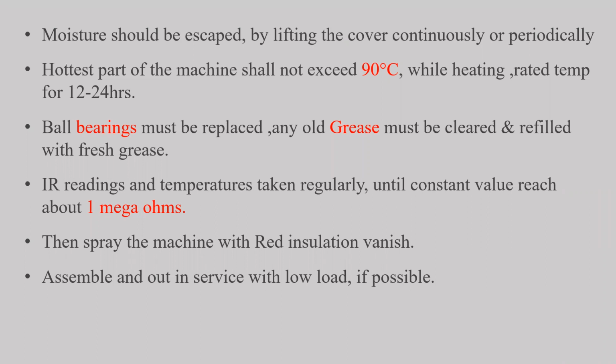They are measuring the insulation resistance, and the temperature is taken regularly, which should not go beyond the limit. Until the constant value reaches about 1 mega ohm, which is the safety level of the windings. So 1 mega ohm insulation resistance is required.